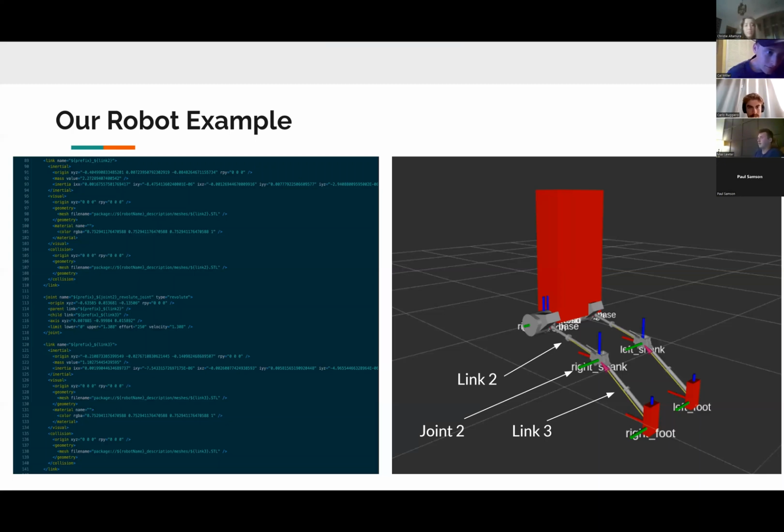It's a framework that gives you exact steps to create a link, and you can add inertia. That's where inertia is added, and then it's an added thing for Gazebo. If you want to get physical results, like the force that your step is going to make, then you do have to have inertia in your URDF.